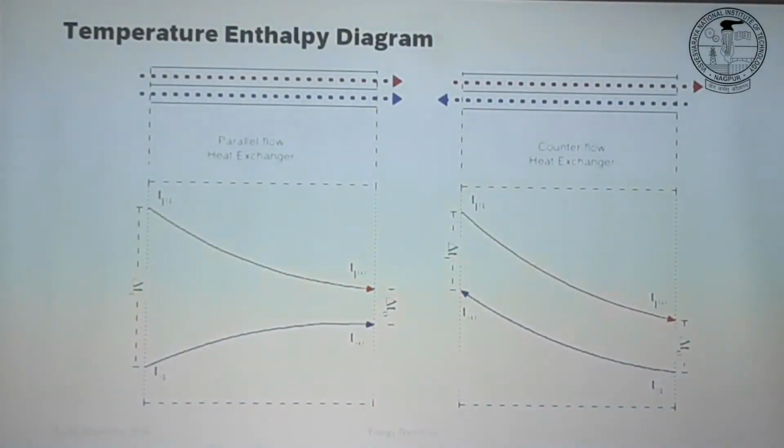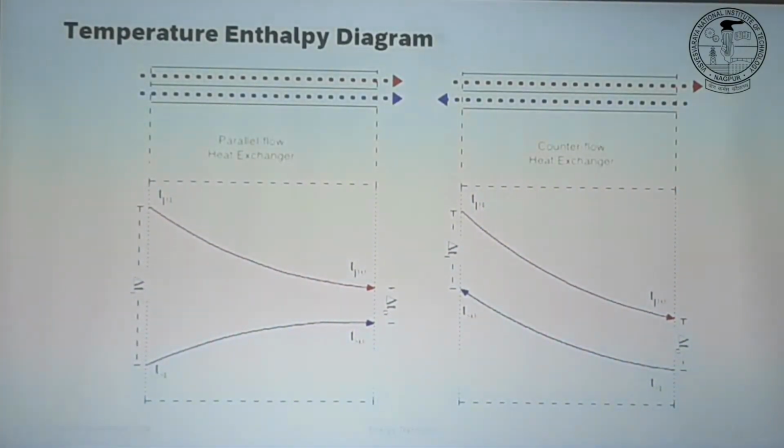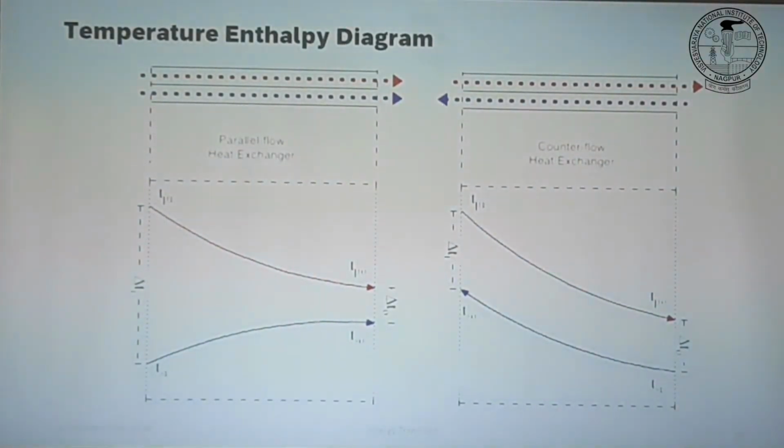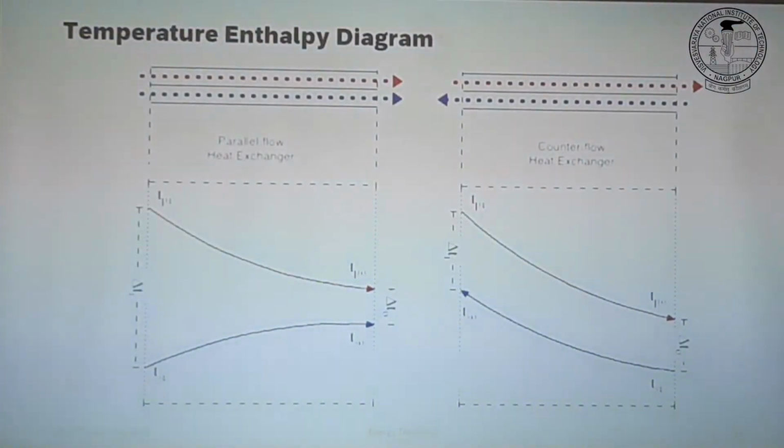Another example we saw yesterday, the boiler, where we have this metal dusting corrosion, and we didn't want to have the temperature window of 400, 700. And we said we go from 800 to 350 directly, thereby having water on the other side. So there also we use co-current. If we use counter current in that scenario, what can happen?